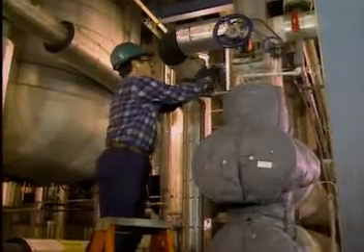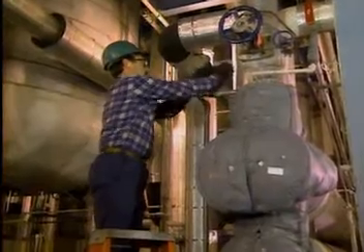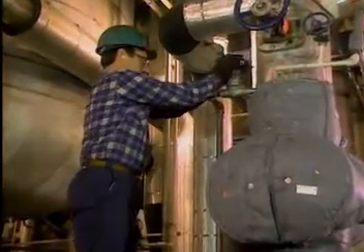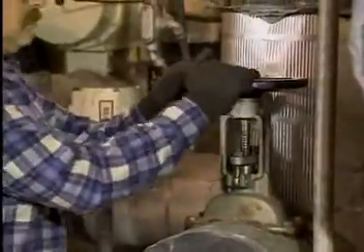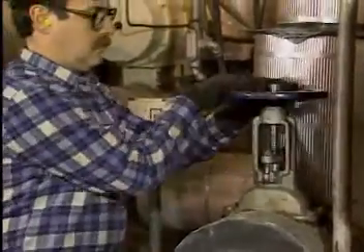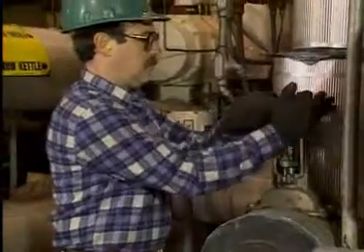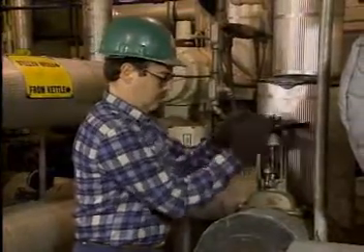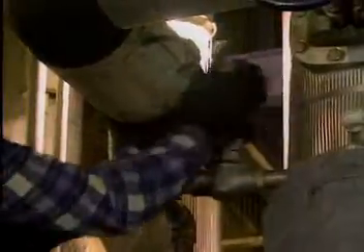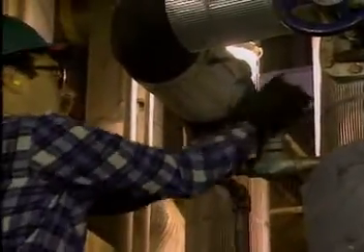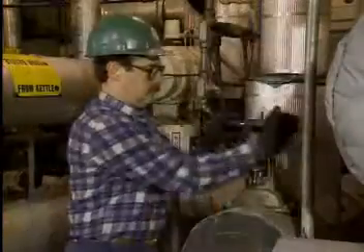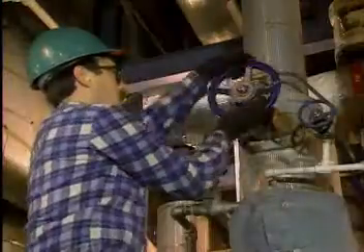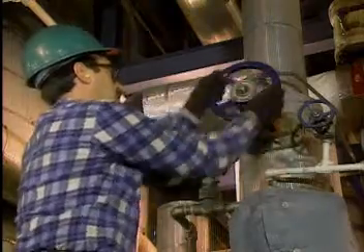The next step is to line up the tube side of the heat exchanger. First, the operator opens the tube side vent valve. Then he partially opens the tube side inlet valve to allow the tube side to fill with process liquid and to remove any air or other gases that might be trapped on the tube side of the unit. When the tube side is filled, the operator closes the vent valve and opens the inlet valve the rest of the way. Then he opens the outlet valve.